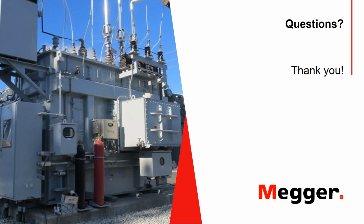Going back to school days, you always remember that a capacitor stores energy in the form of electrical energy, and an inductor stores energy in the form of magnetic energy. If you are testing a winding, you are testing a coil which has resistance and inductance. When you apply a DC current to that, the inductor is storing that energy. If you were to stop the test and not discharge, that energy is trapped in the inductor.